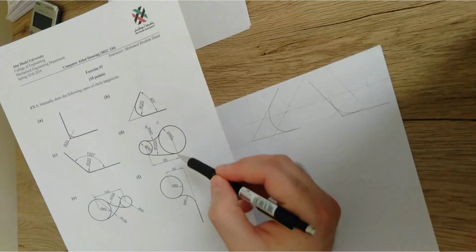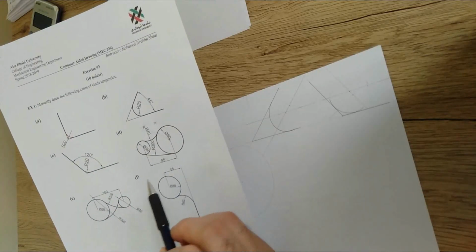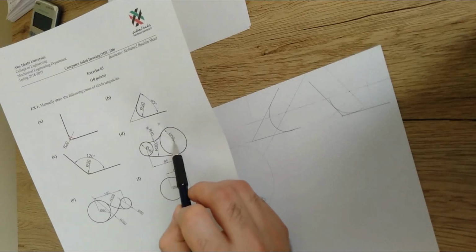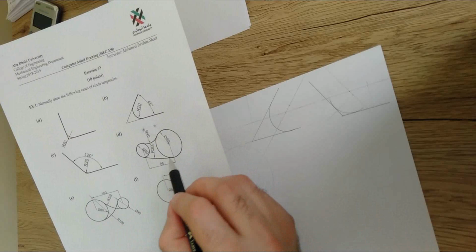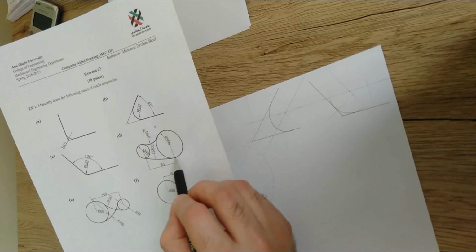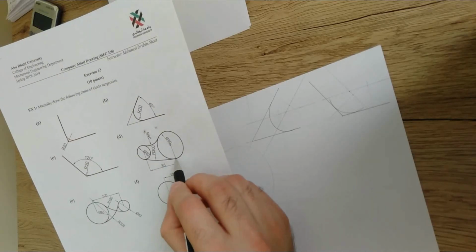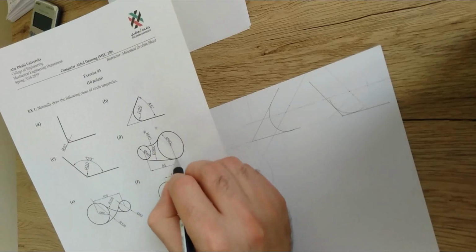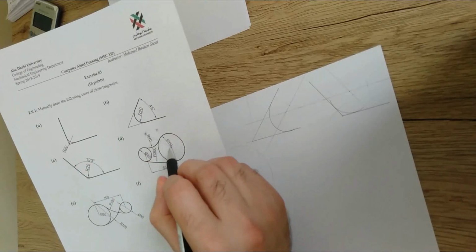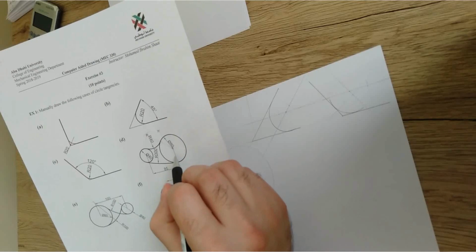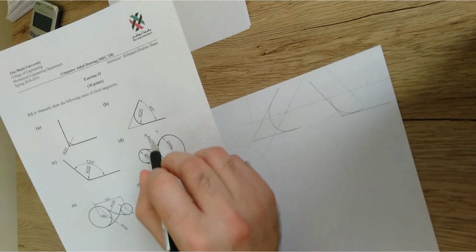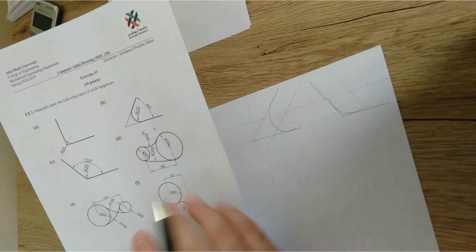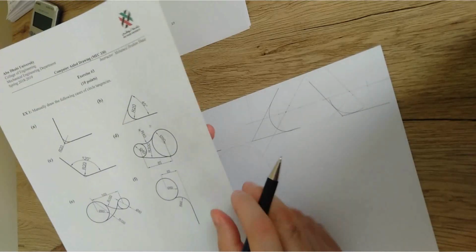Then you're just gonna ask yourself, how much is the distance between the center of this curve to the center of this curve? This distance, for example, from the tangent point to this center, all of this distance is 300. So if we subtract the radius of this big circle, this is gonna give us the distance, which should be 300 negative 40. Make sense?